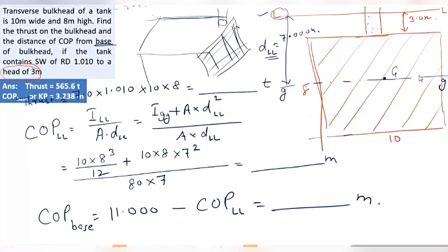I answered that a while back. Is the water in the air pipe part of the tank? Yes or no? Yes, sir. If the liquid belongs to the tank, then wherever the surface of the liquid is, that is the liquid level. Correct? Yes, sir. So it does not get added to the area, but it is part of the liquid. So the liquid level will be where the liquid ends, right? Right, sir. That is why when you do the pressure testing of your bulkheads, you fill water into the air pipes up to the top, because that exerts head on the bulkheads, right?